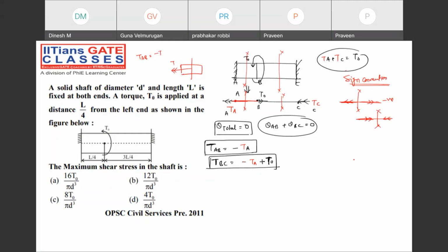We are representing the loading condition from the twisting. It is a twisting loading diagram. We are representing it by a double arrow, not a single arrow, a double arrow. That's the method. When you are moving from the left hand like this and you find a load like this, keep it as negative. When you find it like this, keep it as positive. Whenever you are moving from this hand, at any particular cross section, the load shown something like this will be negative.